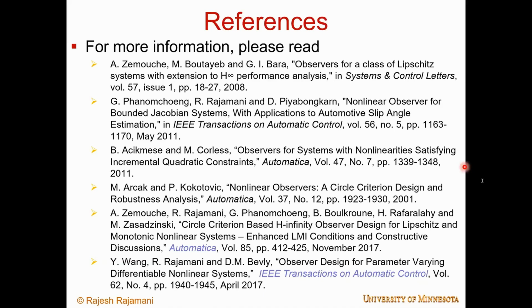Okay, so there is some question about the unknown friction term. One way to address that situation would be to treat the friction coefficient, or a variation from a nominal value of the friction coefficient, as a disturbance. The other way to do it would be to estimate the friction coefficient by using the longitudinal vehicle dynamics and then use the known value of the friction coefficient in the slip angle estimation problem.